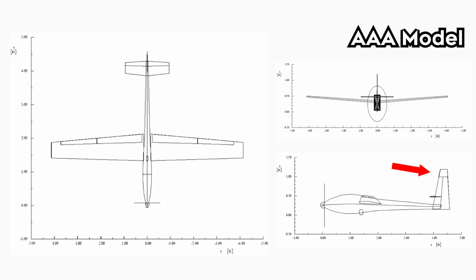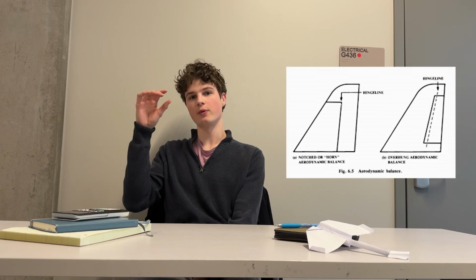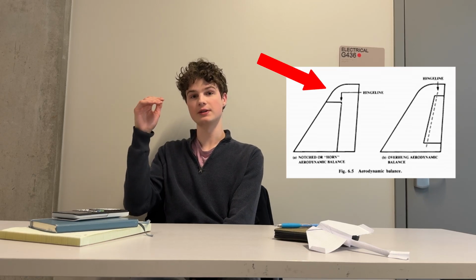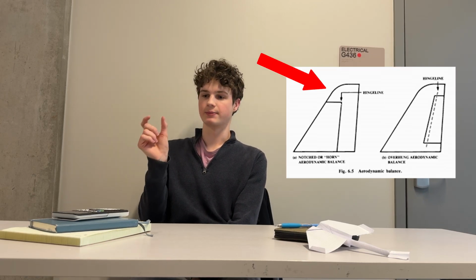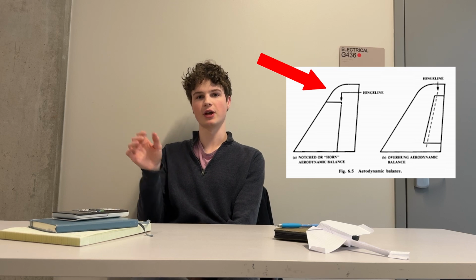The vertical tail is also, again, mounted at the end of the fuselage, and it also extends off of the end of the fuselage. It features a rudder with an unshielded rudder horn. What this means is, yes, the rudder spans the entire vertical tail, but also at the top, where the moment arm is greatest, the rudder doesn't just span the aft portion of the vertical tail, but the entire vertical tail to increase control.